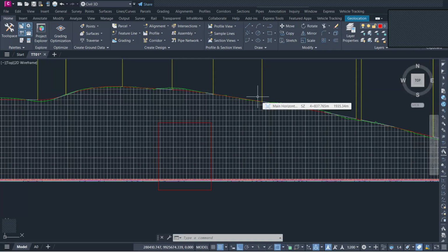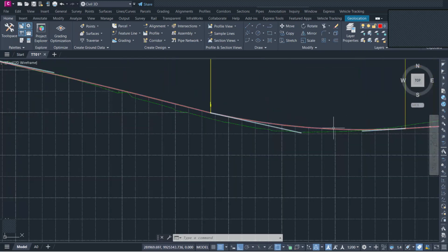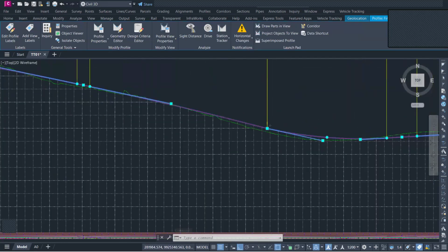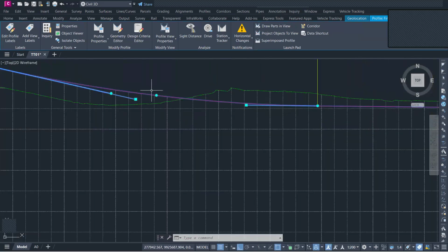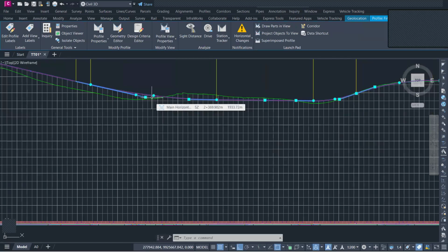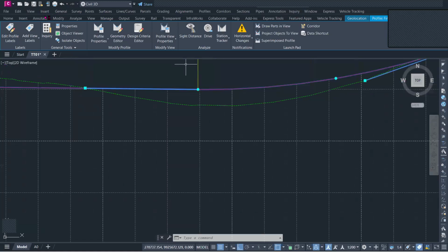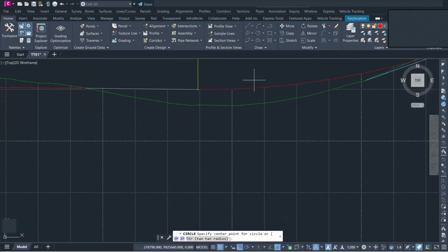So that is the principle. Now, how do you integrate that in design? This is how you do it. Now you are positioning these sag curves here, because that is where the culvert goes, and you must know the exact chainage. Again, you do these inspections on site to confirm that this is going to work for you. Basically, this is the manual method of doing it.